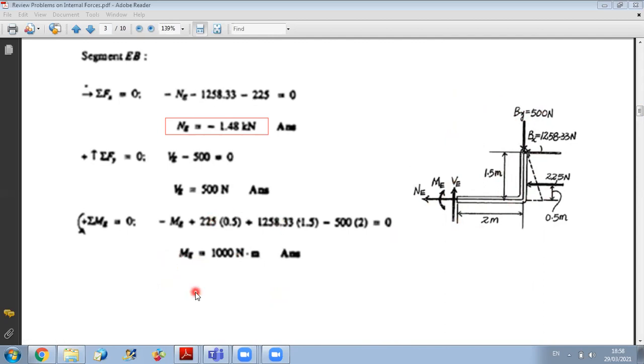Any question on this? As you can see, the internal forces are like a review for the equilibrium chapter. If you understand the equilibrium chapter well, it's just a small application. You should know how to do your cut, and once you do your cut, how to put the convention for shear, normal, and bending. Then you can deduce what the internal forces and moments will be. Okay?